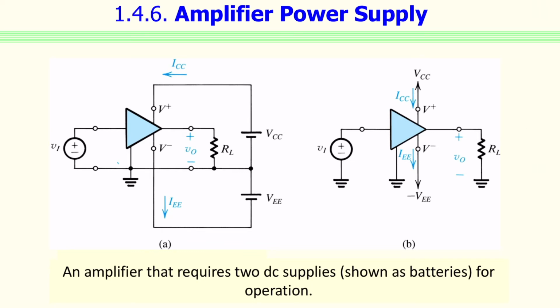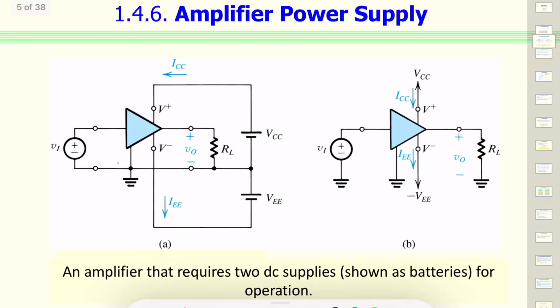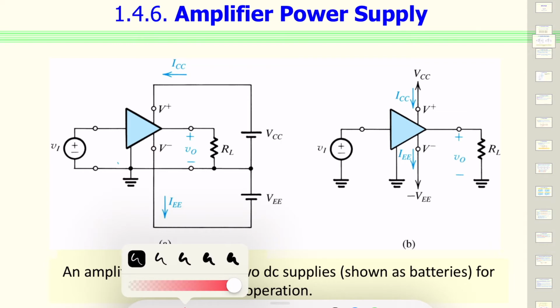The power delivered to the load is many times greater than the power that's drawn from the signal source. So this amplifier gets this DC power supply to do the operation. These power sources supply not only the power that's ultimately resulting in the amplified signal, but also those powers that may get dissipated in the process.